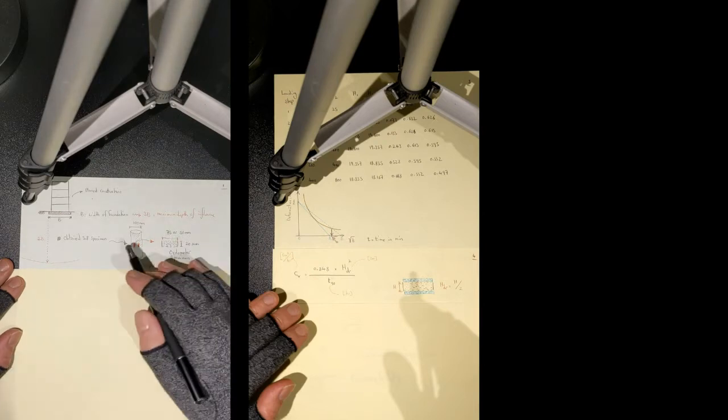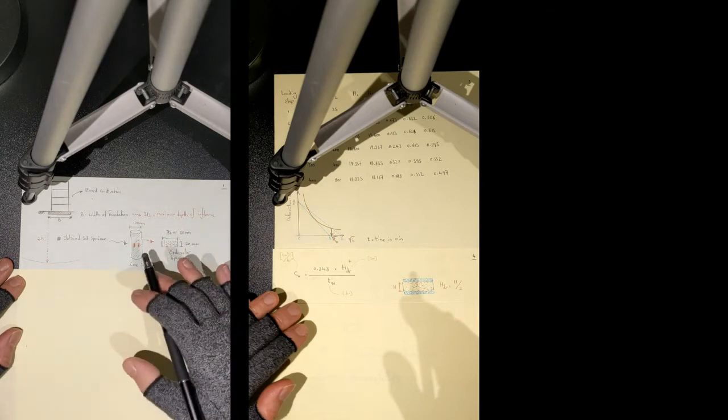So Shelby is more American, U100 more British. And the diameter of your soil sample is 100 millimeters. That's why the mold which you push into the ground is known as U100. And the height really varies. It's a core sample. And you will wrap your soil sample and send it to the laboratory. Now, in the laboratory, you need to retrieve a soil specimen from this soil sample. You will retrieve a number of soil specimens from your soil sample to do a number of different types of tests. Today, you're only interested in consolidation tests.